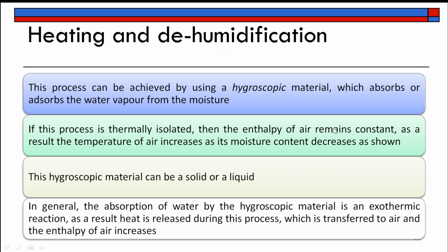Okay, so that absorption of water by hygroscopic material is an exothermic reaction. As a result, the heat will be released. Exothermic reaction, heat will be released out, which is transferred to the air and enthalpy of air increases. So both will happen simultaneously, heating as well as dehumidification.